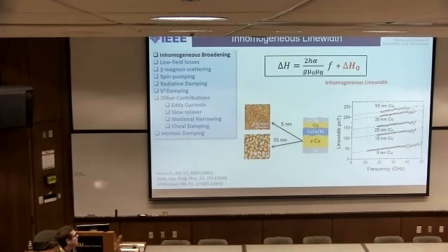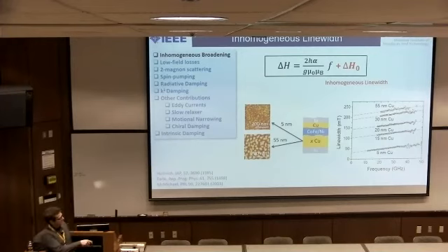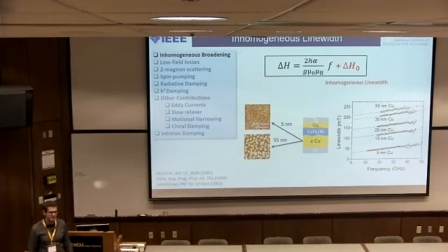Yeah, I mean, this is actually rather old data. It actually comes out that our waveguide just isn't very flat in its response there. So you get these regions where you get much higher signal to noise, and you might get these little wiggles out. It's a function of our microwave circuit, which we've improved on since this time, but you can get little resonances in your waveguide and things like that that cause that. And of course, your signal to noise drops as you go to higher and higher frequency because the losses in your microwave circuit get larger and larger the higher frequency you go.